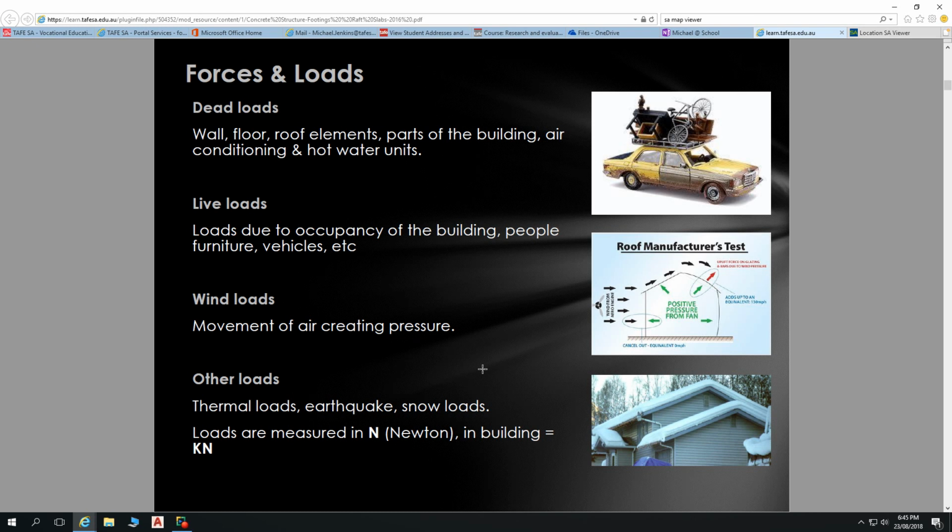We've got a new fire station out where I live. One of the first things I noticed in there was the bracing sags in the roof. There's big sags in the bracing. So that bracing is not active, and it's not going to become active until there's a lot of deflection happening on that building. That building's going to be partially twisted before that bracing is activated. So bracing in your frame does need to be very taut.